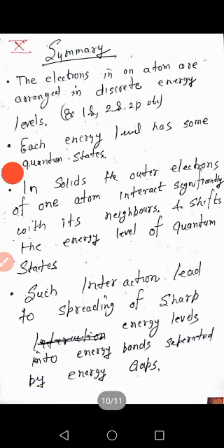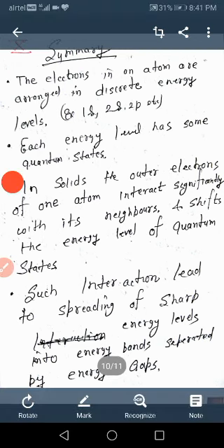And in different atoms we have seen there are different kinds of energy bands, and the energy bands are the valence band and the conduction band, but the formation is different. In some atoms the energy levels are 3s and 3p. In some, those orbitals are mixed, and in silicon there is sp3 hybridization.